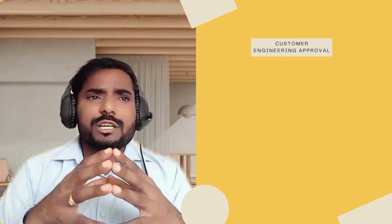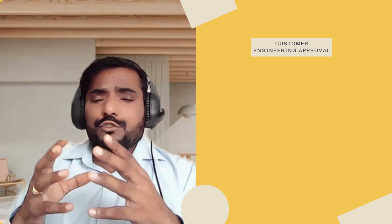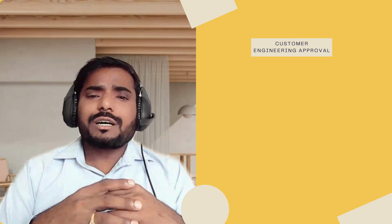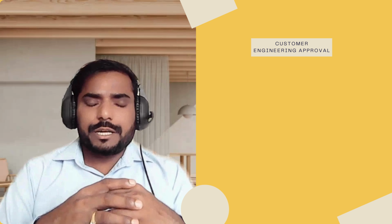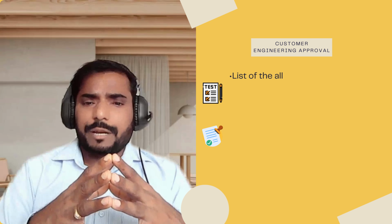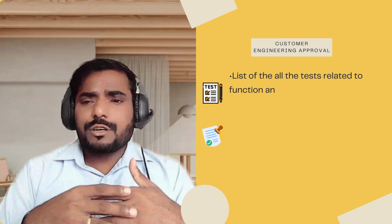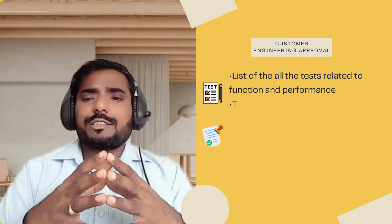Now talking about the engineering approval, the customer engineering approval. Basically, in the customer engineering approval, we call it the design verification plan and report, DVPR. So understand what kind of testing they have captured. Check the list of all the tests mentioned in the DVP, whether they have planned for all these tests, and whether they have done the validation for all these tests.